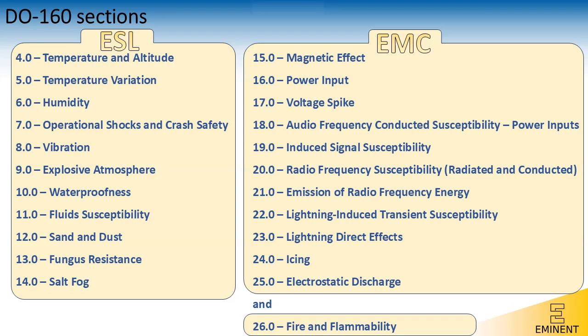Application of DO-160 in design, testing, and certification processes. DO-160 is integral to multiple phases of aerospace product development and certification. Its requirements shape the design, testing, and approval processes, impacting stakeholders from initial design through regulatory clearance. Design phase: engineers and designers consult DO-160 specifications early in the development process, ensuring that materials, construction, and system configurations align with environmental standards. For instance, designers of avionics components take into account DO-160G's electromagnetic compatibility and vibration requirements to ensure long-term